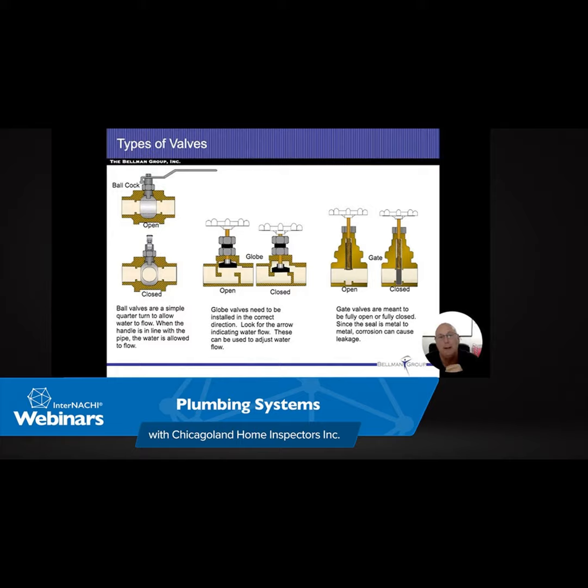All right. So these are going to be test questions. You do need to know these items here. Any water pressure on a supply system between 20 and 80 is considered acceptable. In our area, 40 to 70 is what's kind of normal. Anything under 20, you're going to need a pump. Anything over 80, you're going to need some sort of pressure reducing device.